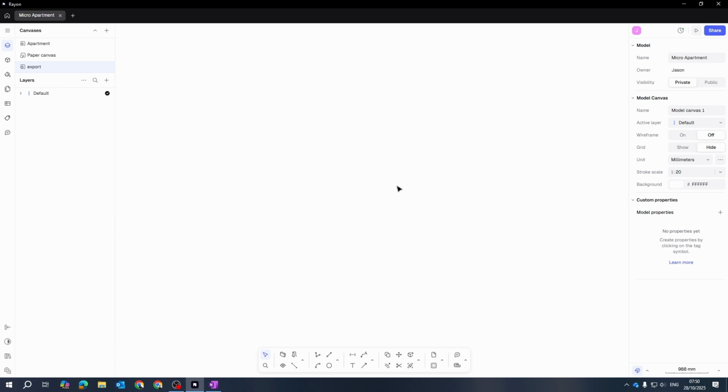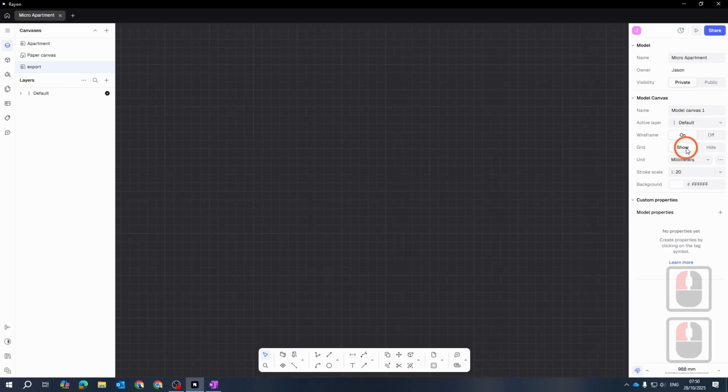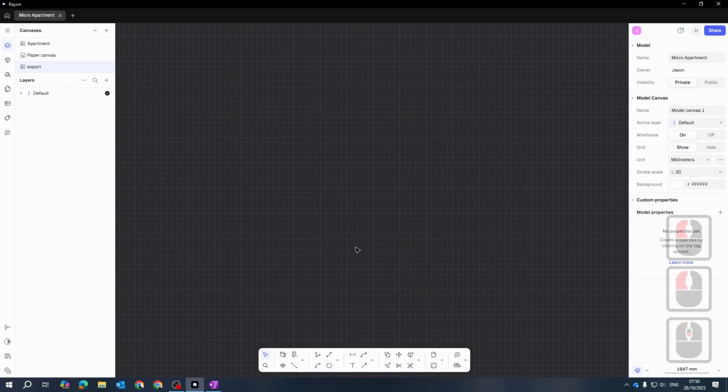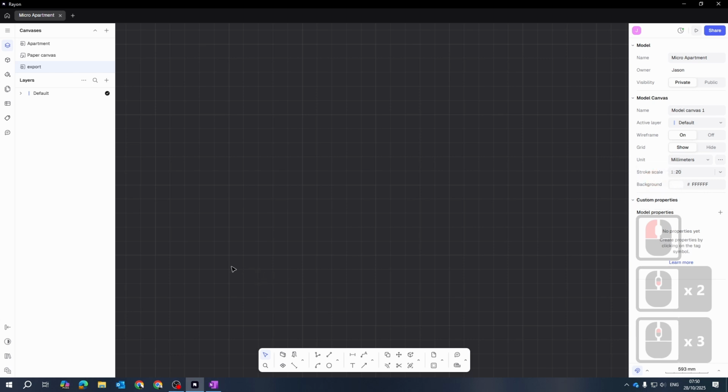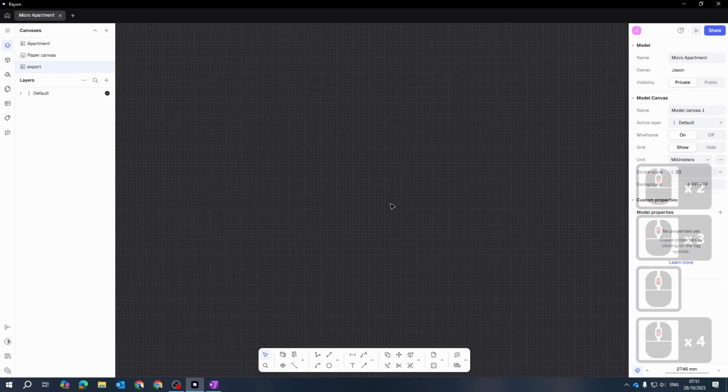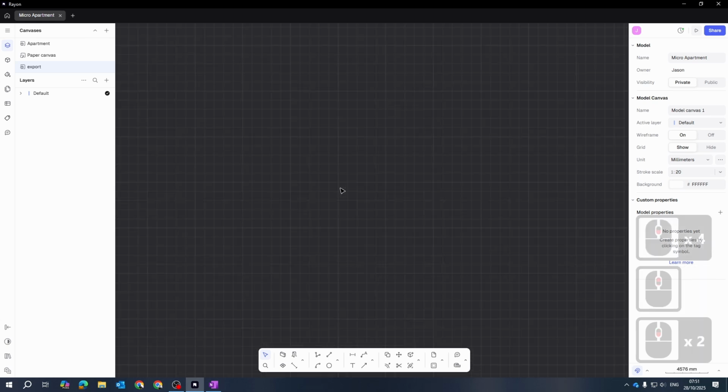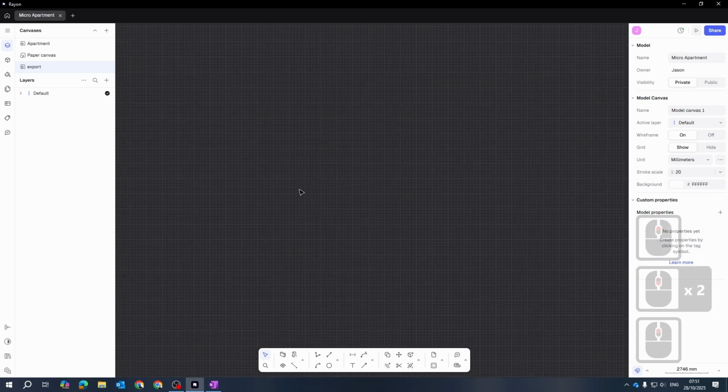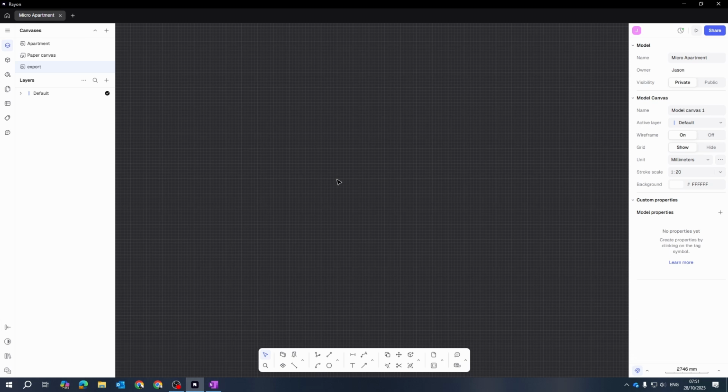Okay. Now, this is something that I have picked up with helping some of you in the studio. If you switch on wireframe and you say show grid, now this is very hard to see, but there is an origin in there, a little green dot that appears. You don't see it straight away, but if you get to a certain zoom, you'll see there's a green dot. Now technically this is the origin of this file, and this is quite important when you want to export stuff to